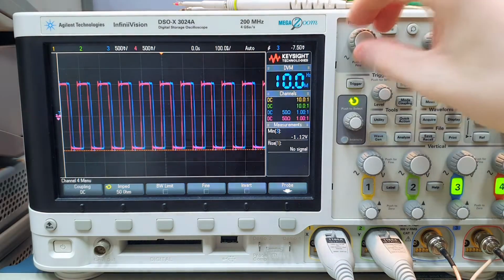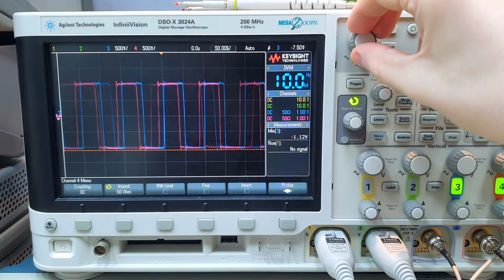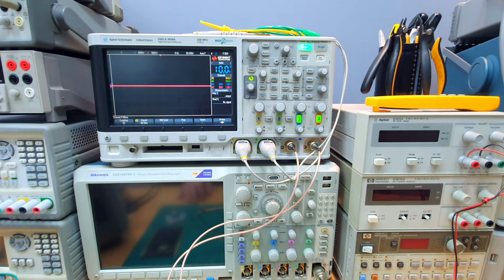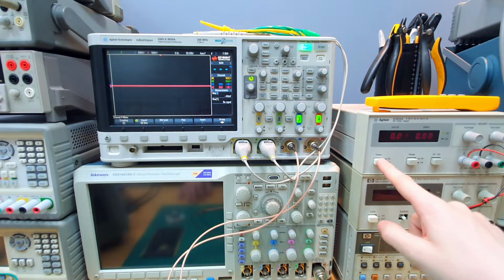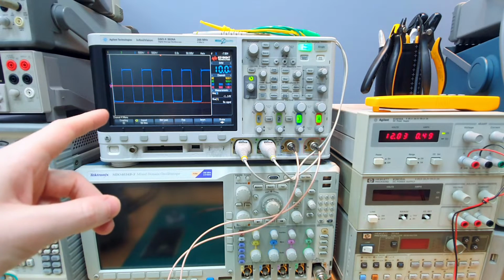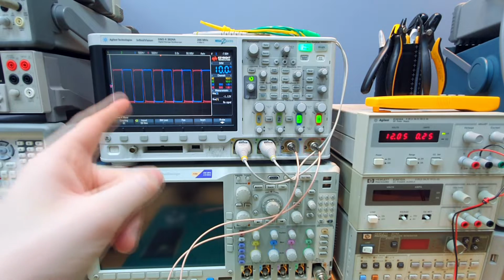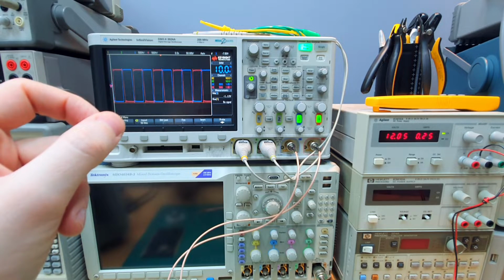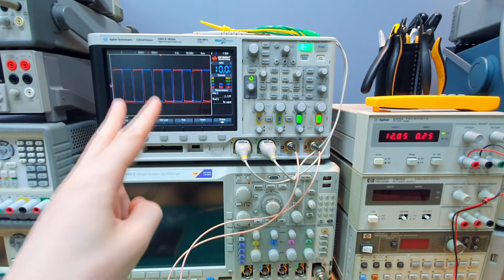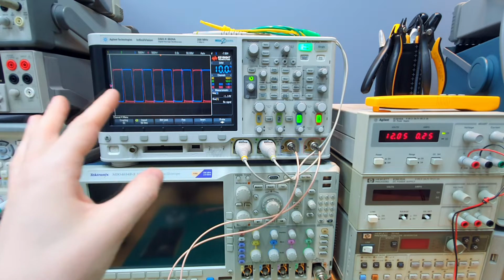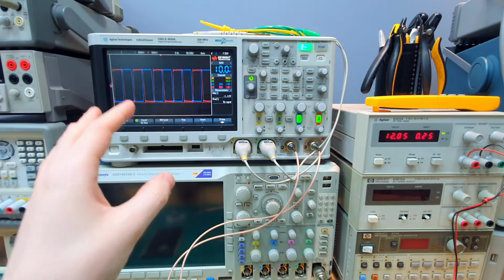I'm not sure why the phases are misaligned here, probably a configuration of the IC. We see that by default we got 10 MHz on the output channel A, and then channel B comes with a different phase. That's very interesting. So probably the IC uses different PLLs for each output, and we have a configuration for alignment of phase, or something like that.